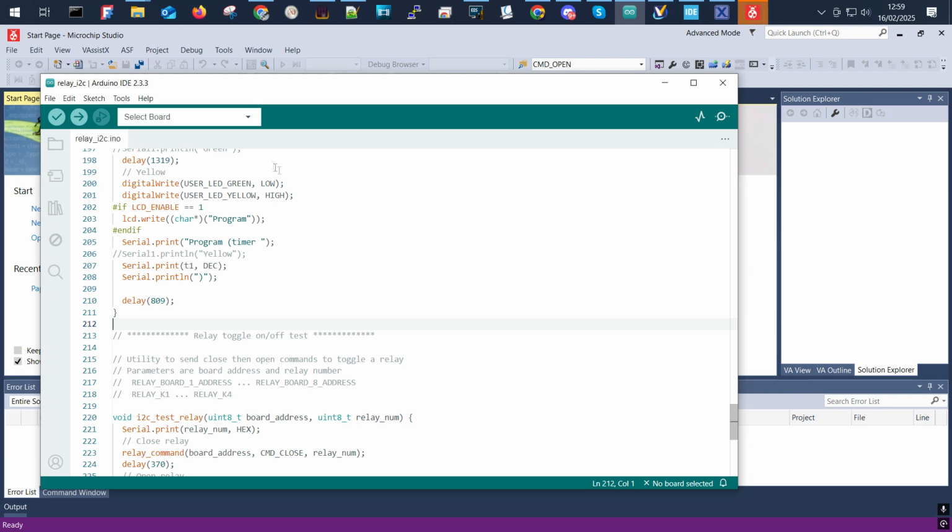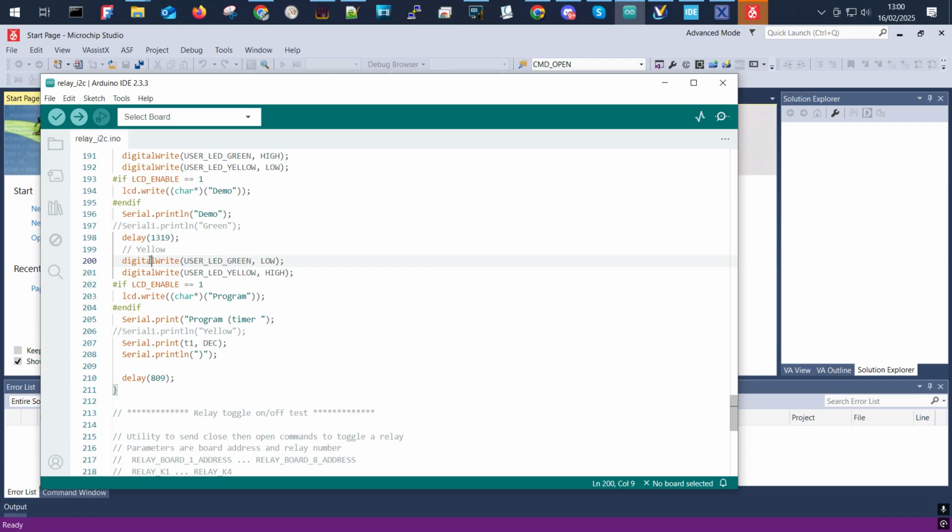We can be limited by the implementations used in the underlying library, like the serial library. The digital write library is also going through indirections. That is, we don't just write the pin low or high. This actually goes into a lookup table to see what is the pin for this particular microcontroller.